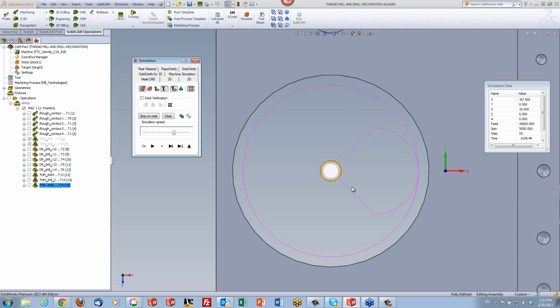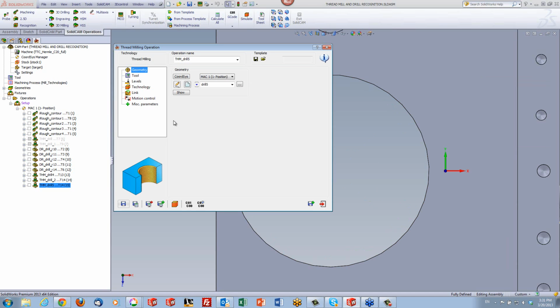And what I'd like to do is actually shorten this to work directly onto this arc over here. What I can do in this particular case, since I'm working internal, if I go into the link, I'll say you have either start from center or without start from center.